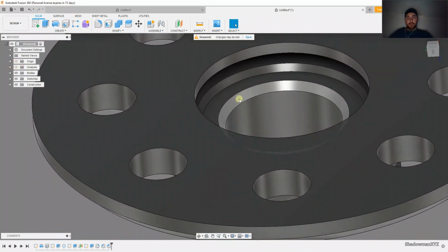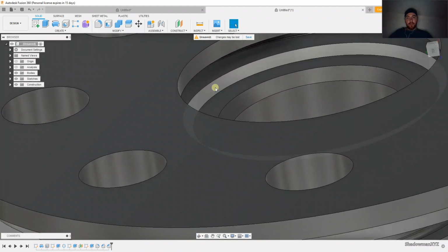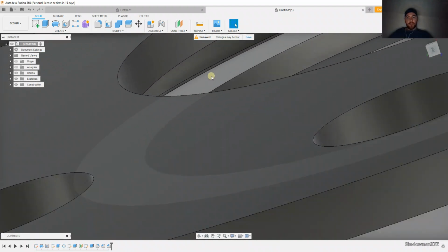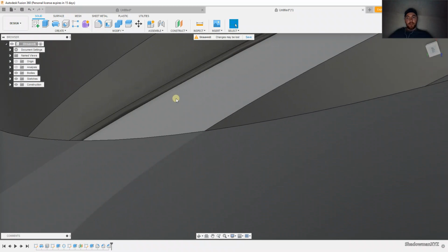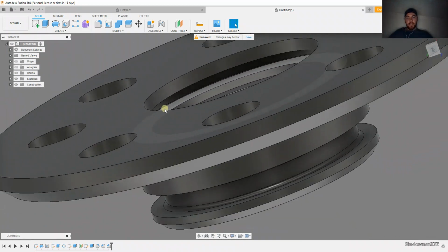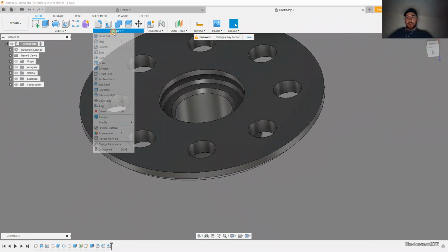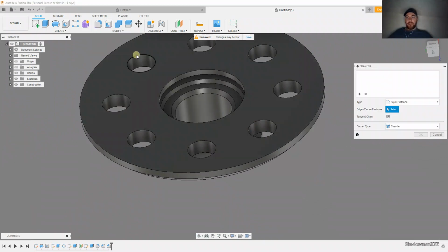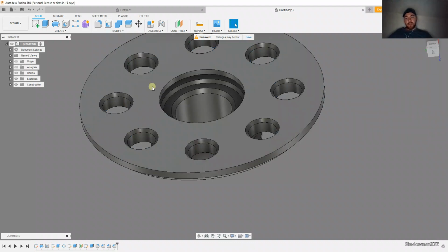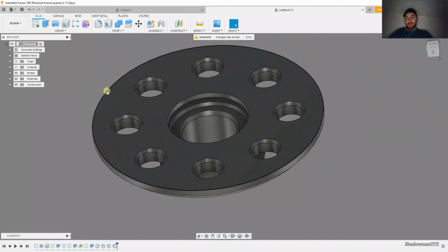See, we put that chamfer in that bore, put the groove, put radii down in the corner. See how this part's coming together? Say you want these holes to be chamfered. Chamfer, click on the ones you want chamfered, and then give it an amount. Let's say 0.05, 50 thousandths. Your holes are now chamfered.